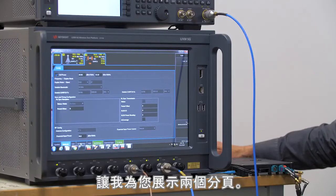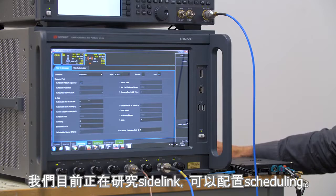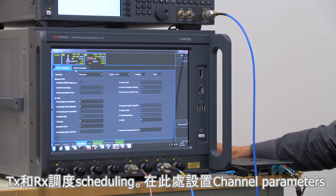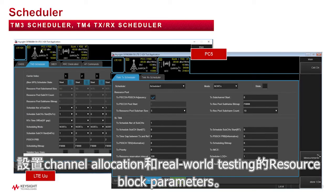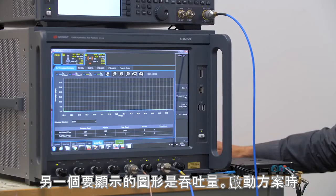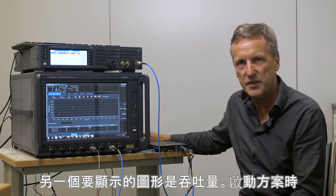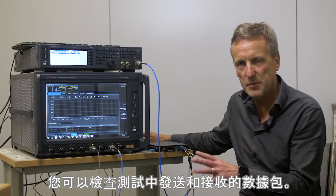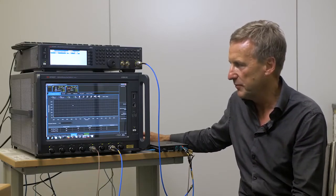A couple of tabs I'd like to show you. Here we're working on the side link, and we can set up what we call our schedulers, both transmission and receive scheduler. These set up the channel parameters for allowing the channel allocations, the resource blocks, to be set for testing in a real-world environment. The other graph I'm going to show is our BLER throughput, and when I start the scenario, we will see the packets being transmitted and received as part of the test.